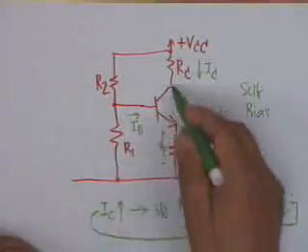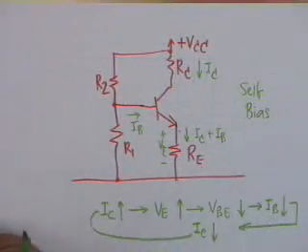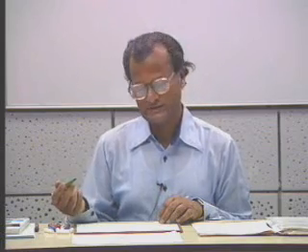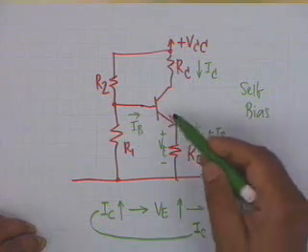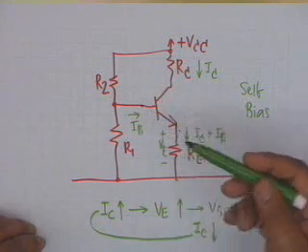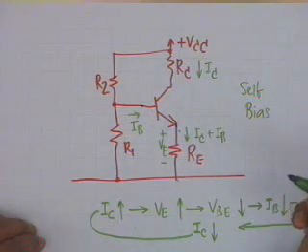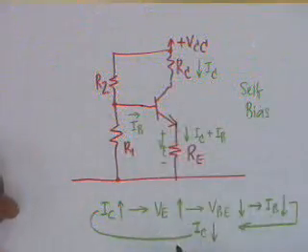This was one of the main causes why the previous circuit could not be used, because that had kept IB constant, and therefore if we replace the transistor, the beta of the transistor, as you know, can have a spread of about 1:6. Irrespective of whether the transistor is replaced, whether temperature increases or decreases, I sub C should remain a constant. Let us see analytically how this happens.